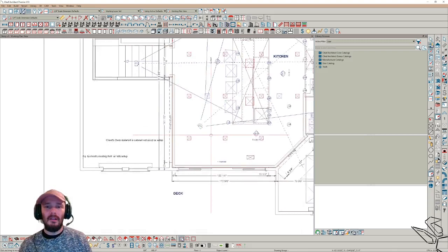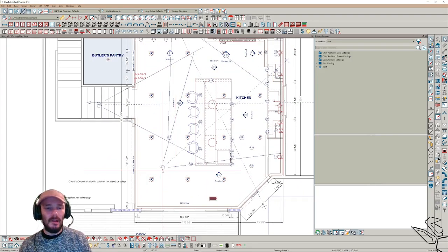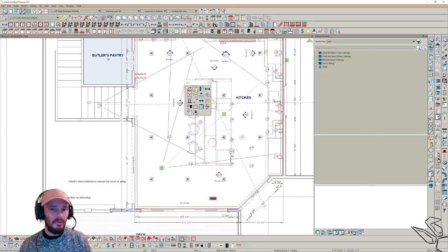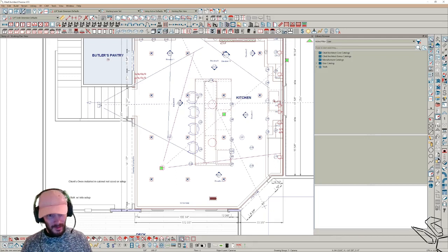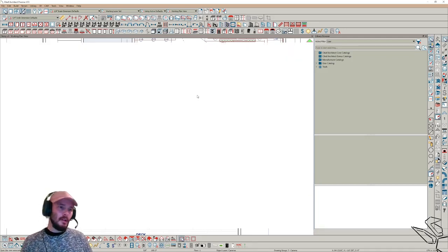So here we go. This is that scene. I will say it's super important when you're doing these spherical renderings to save your cameras. Make sure you save your cameras. That way, when you find an error, because it takes a long time to process these things, you can come back and re-render.